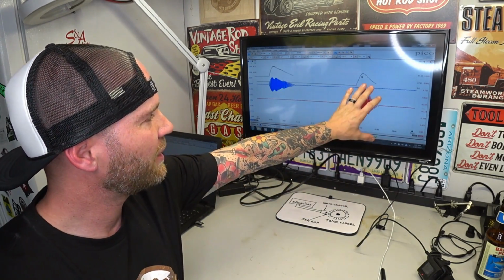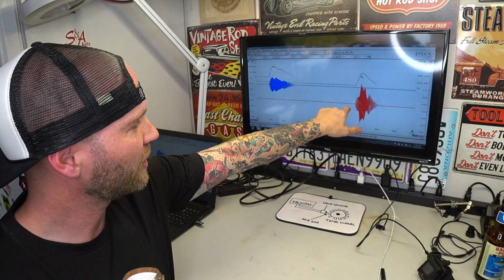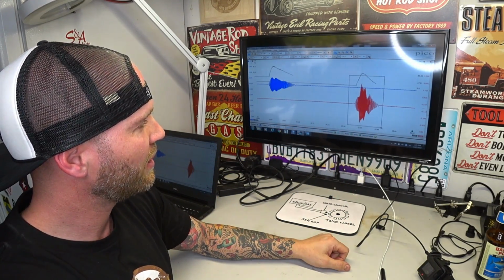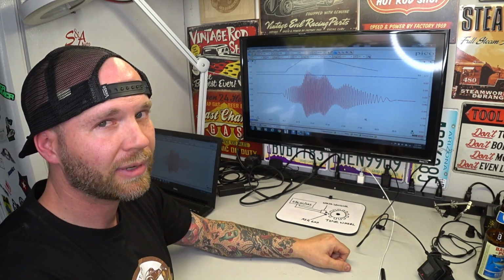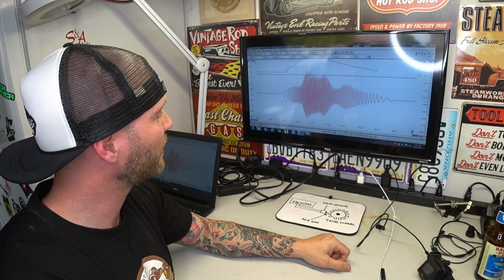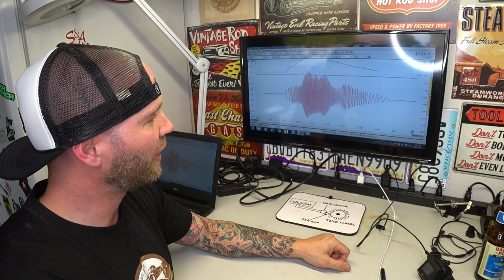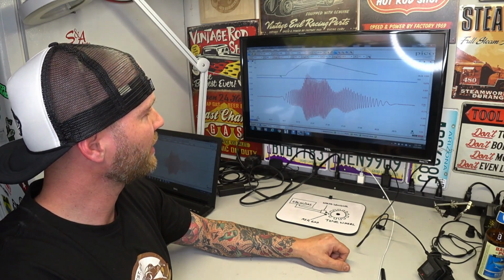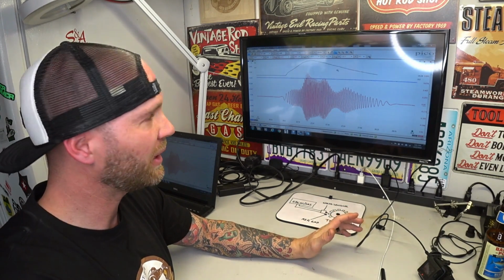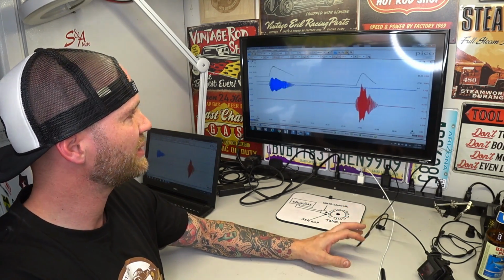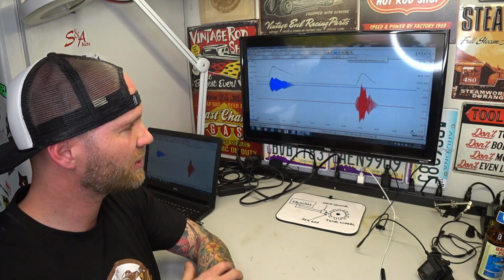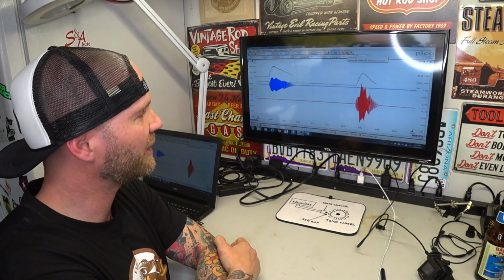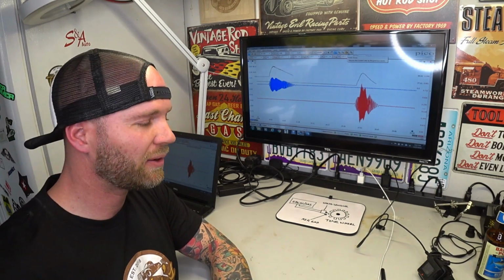Are you going to be able to pick up these kinds of signals, the AC signals from the wheel speed sensors, on a Snap-on scope? Absolutely, you are going to see this. Are you going to be able to add the frequency? No, it's limited when it comes to that. But the Snap-on scope is good. Just the AES U-scope, awesome. Having a scope is better than having no scope.